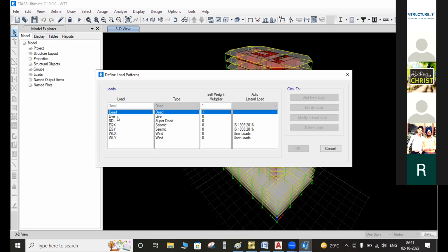So okay, this is the load pattern. Load combinations we will take later. Whatever loads we are considering depend upon the code provision, sir. When we use the Indian standards, on the basis of IS 875 part 1, we are calculating the super dead load. It is a branch of the dead loads, whatever the type of finishings, the masonry, identifying the thickness and density, we calculate and apply.